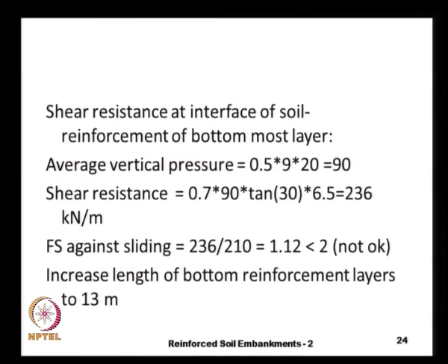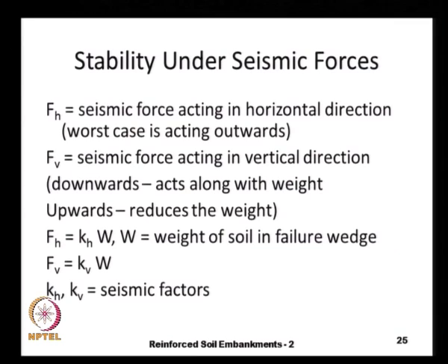And so far we have discussed the stability of slopes under static loading, but in many cases we will have to design the slopes even for earthquake forces. Now let us include the additional forces that we have because of the seismic forces, and let us say that we have two extra forces.